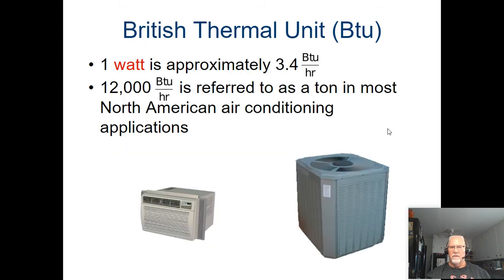So what does this mean for calculating our heaters and our air conditioning? This is an important part. You may want to write this down. You're going to need this in the activity. So if we're talking about heating, how many watts of heating do we need? Well, 1 watt is approximately 3.4 BTUs per hour. So typically we figure heaters in BTUs per hour. So if we need to raise 3.4 BTU, we need 1 watt to accomplish that.